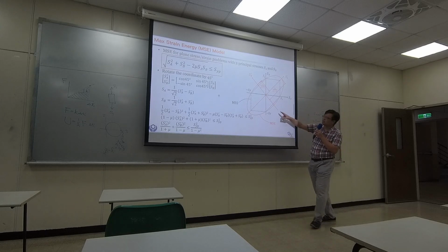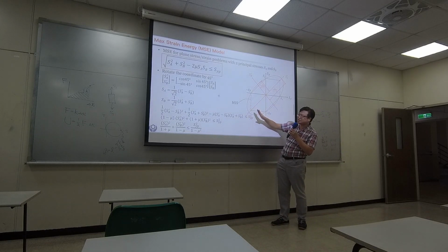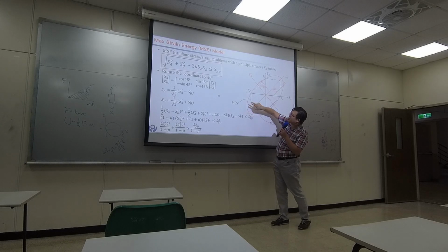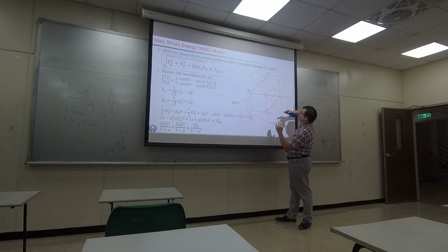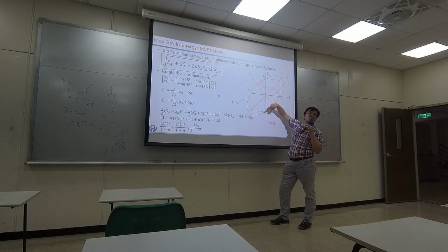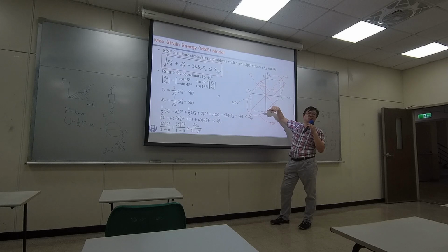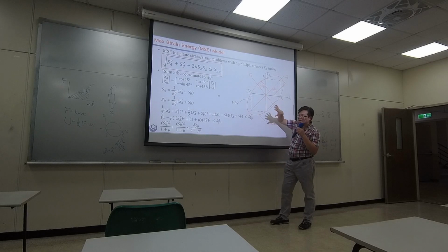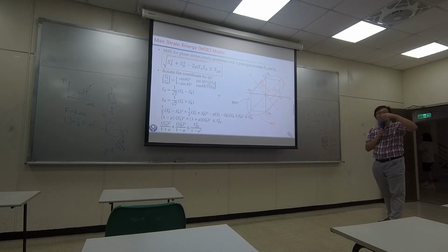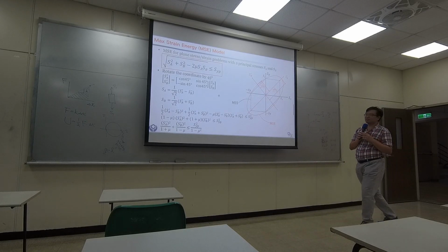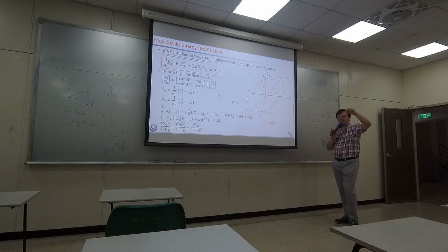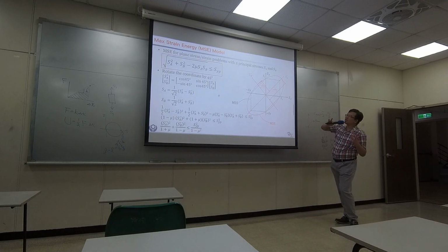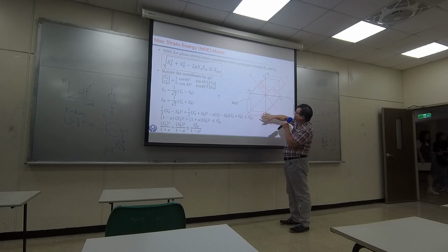So from the maximum strain energy model, this red ellipse is typically, usually, or always wider than the dash boundary from the maximum shear stress model. So this maximum strain energy model is less conservative because you have a greater design space. You allow your design to have a greater freedom to carry loads.